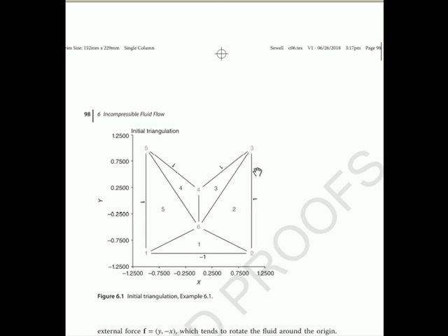No flow just means U and V are zero, so that's like a sticky boundary where the fluid can't cross the boundary, but it can't go parallel either. On the bottom we got free flow. That means that V can't be zero because it can't cross the boundary. This is a solid boundary here, so the fluid can't go perpendicular to the boundary anywhere. Here it can't go horizontally either, so the U and V are zero on all the boundary except the bottom,